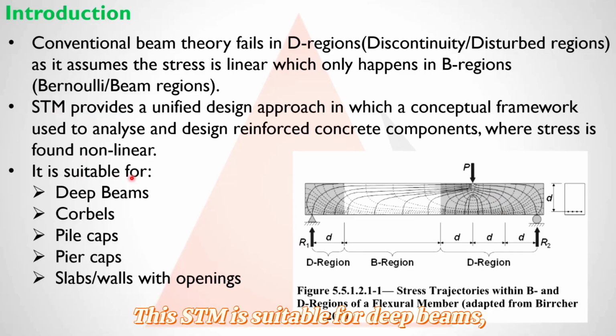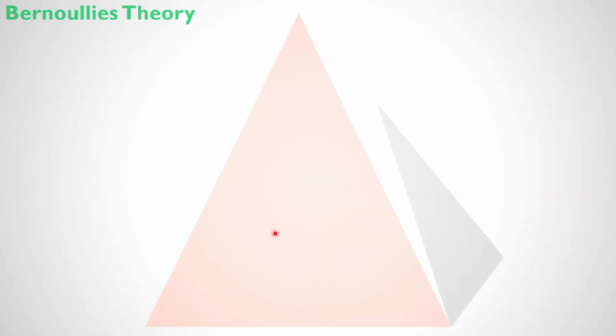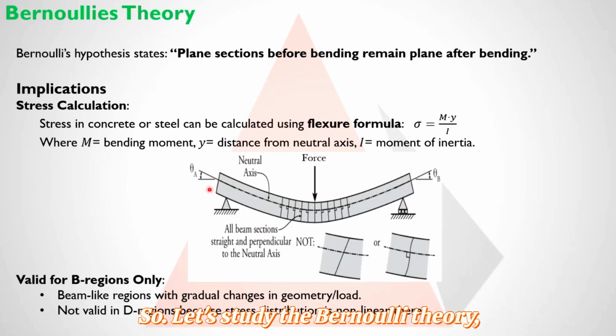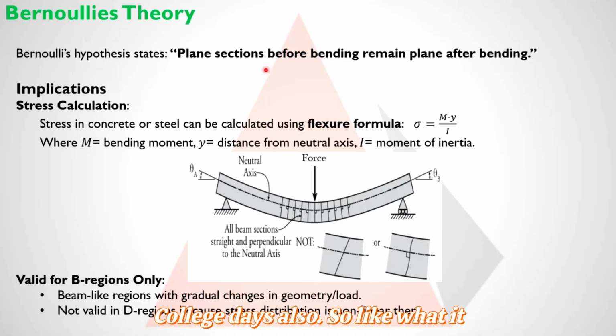This STM is suitable for deep beams, corbels, pile caps, pier caps, and slabs and walls with openings. So let's study the Bernoulli theory, what it states. It states that plane sections before bending remain plane after bending. This is a very normal and basic thing that we learn in our college days also.